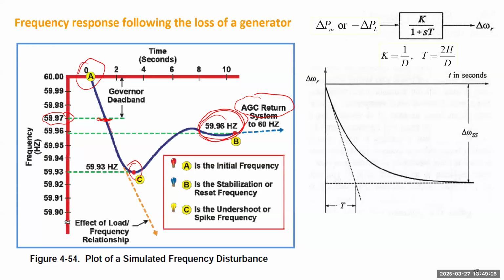we already solved that the frequency will decline following this relationship. If there's no frequency dependent load, this is almost like a straight line. But if it has inertia and a frequency dependent load, it will finally stop at some largest frequency deviation, but that can be huge, right? It can be much higher than any threshold we can allow the frequency to operate. This frequency declining curve can be solved by this exponential function.